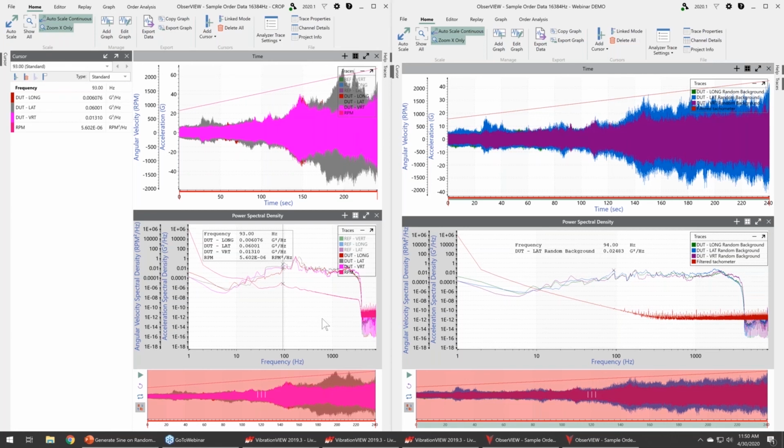I'm not exactly sure what this question is trying to say, but when you run just a sine sweep, a single sine tone at an amplitude, you are driving all of your energy into that specific point and are probably going to get the most energy driven into a resonance as you sweep through it.